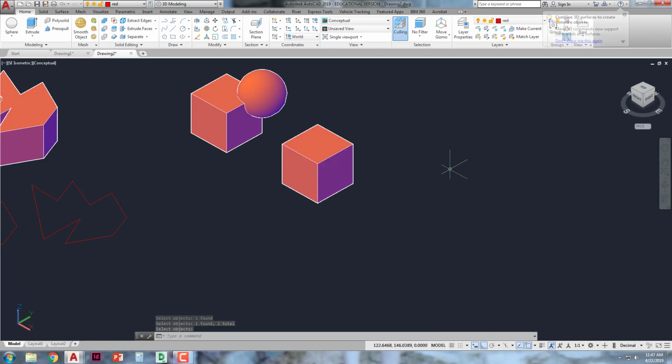So when you're done making objects, you're really going to make them out of the primitives. You're going to have a couple of rectangles, maybe you'll subtract a cylinder, maybe you'll subtract whatever. When you get it all built together, at the very end you want a union. That way you just get rid of any creases or seams or anything like that between the objects. Do not union before you're ready, because you can't ununion. There's no ununion command. You can explode a 3D if you do X enter or just regular explode command.